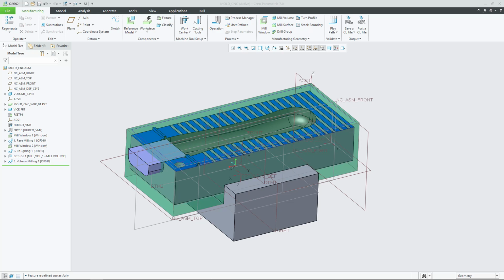That can include the Z-axis as well, so the Z-axis is the vertical, but you generally refer to feed in terms of X and Y movements, and the speed in terms of the rotational speed of the tool. How quickly is the CNC machine spinning the tool in the end of the turret or the end of the chuck. Mixed in with these two values are other values that have an effect on them, and these could all be classified as the cutting parameters.